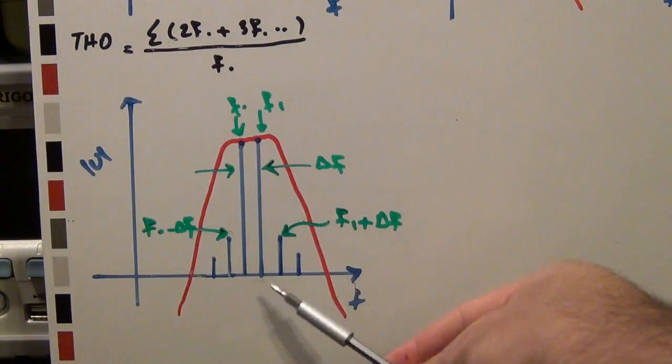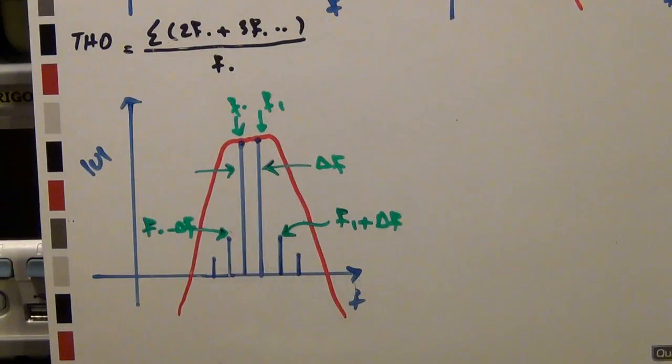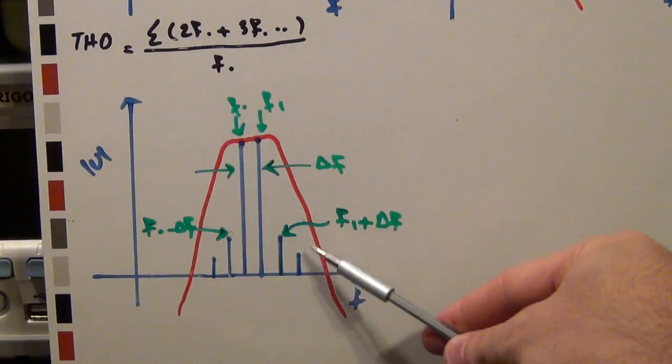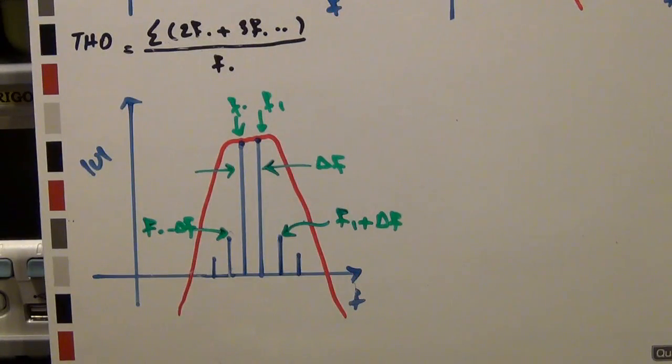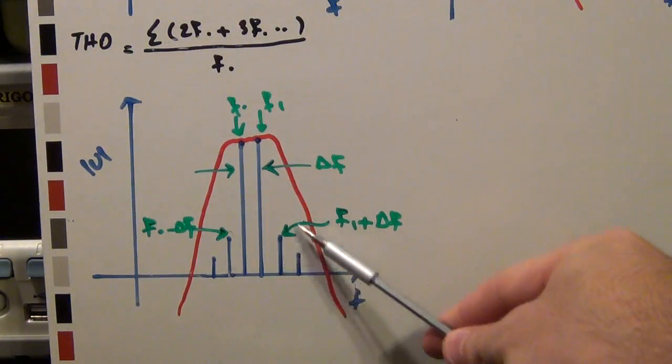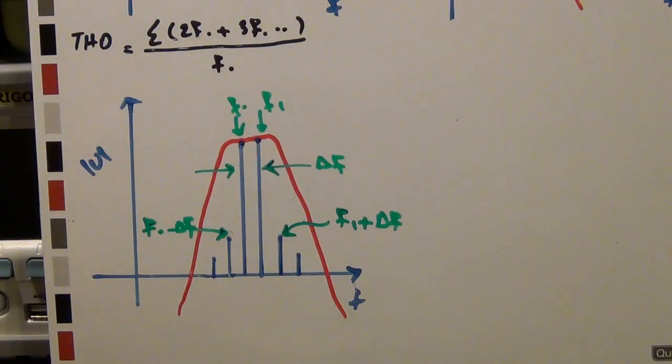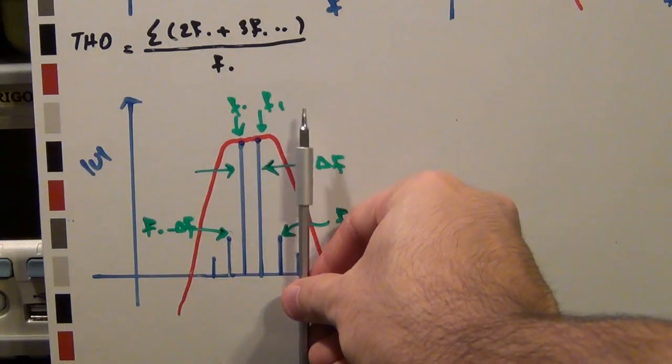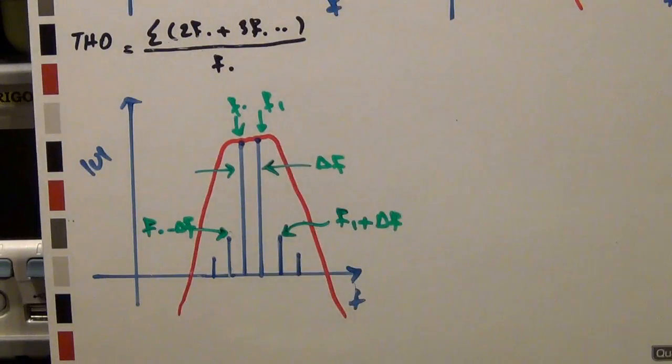So ideally, you put in two tones, you don't want any of these, but these guys creep in because of the nonlinearity. Now in a wireless circuit system, this is very important because this means that by generating these tones, you could actually be occupying your neighboring channels that don't belong to you. So there is another guy sitting here with his own two tones and a different channel trying to send and receive data, but if the harmonics of your signal occupy his channel, now you're fighting him for his signal.